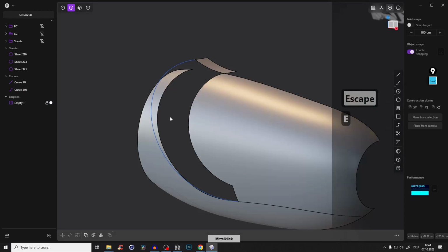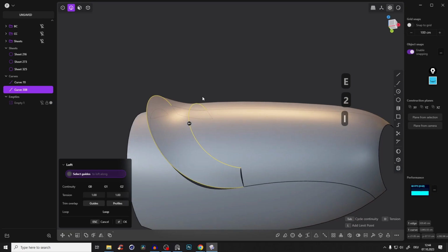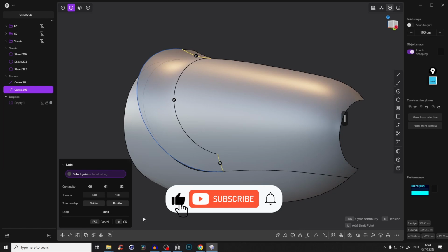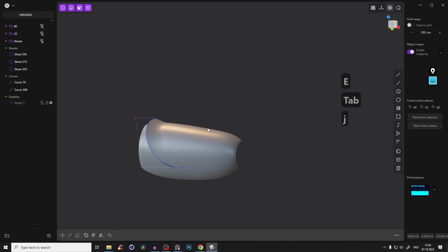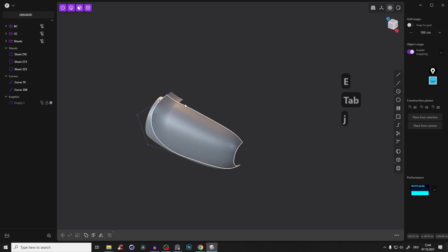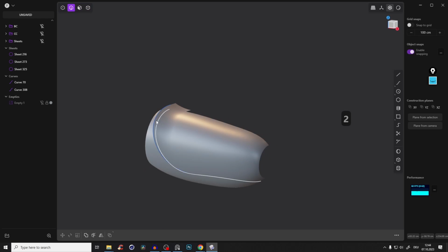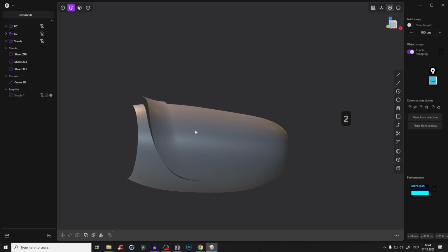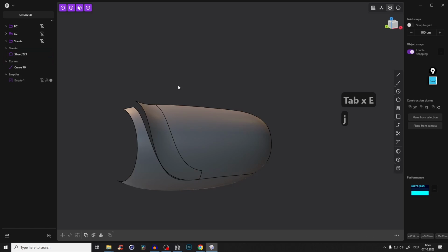So now let's do some magic and select that edge and curve, loft, and you see, and now Shift, we will add this shape here and here back to the surface, everything is G1 and press OK and voila guys. So let's connect that. Isn't that just beautiful? Yes, it's not 100% perfect here, smooth, but for now it's super fine. And this is again a building curve. So bring this building curve into BC and delete that sheet here and let's join everything.